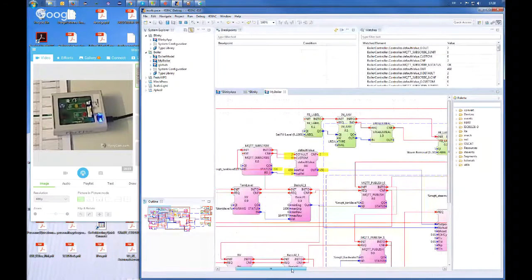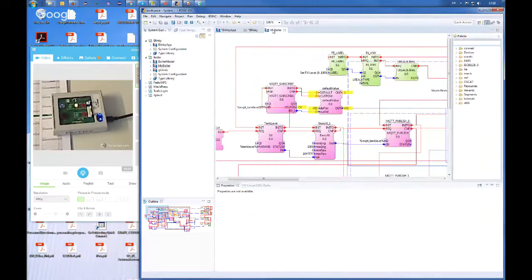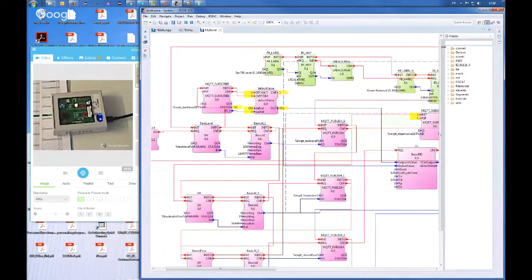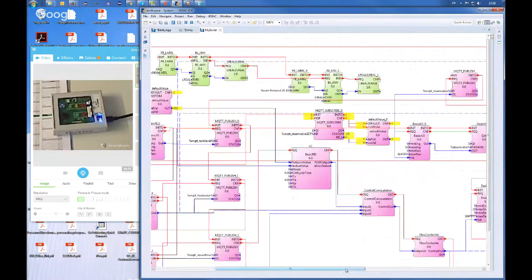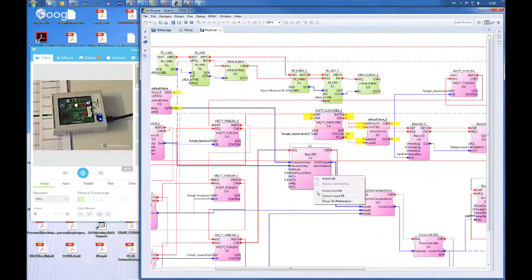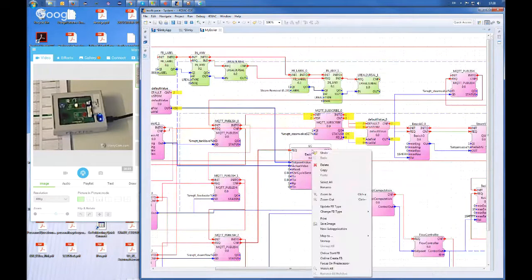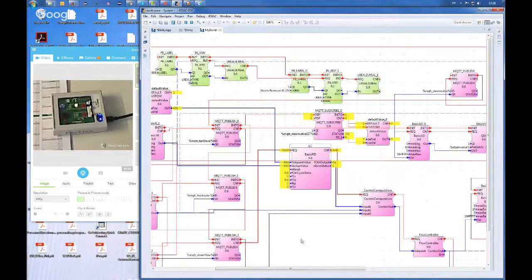So this application is already a little bit bigger. I just make it so that you can see a little bit more. And here is a very classic control algorithm. It's a PID, which is getting the set point, which is currently 450 for our level of the tank, and the actual level is jumping around a bit.